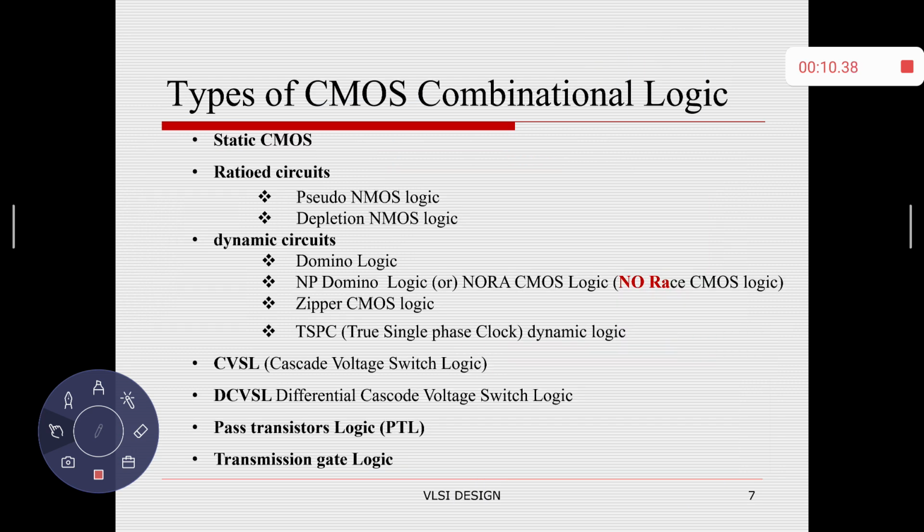So far we have discussed the basic principle of a combinational logic circuit, CMOS, which is a combination of NMOS and PMOS transistors. We also discussed the effect of NMOS and PMOS transistors connected in series and parallel. We conclude that when two NMOS transistors are connected in series, they act as an AND function. When connected in parallel, they act as an OR gate. Likewise, when PMOS transistors are connected in series, they act as an OR function. When connected in parallel, they act as an AND gate.